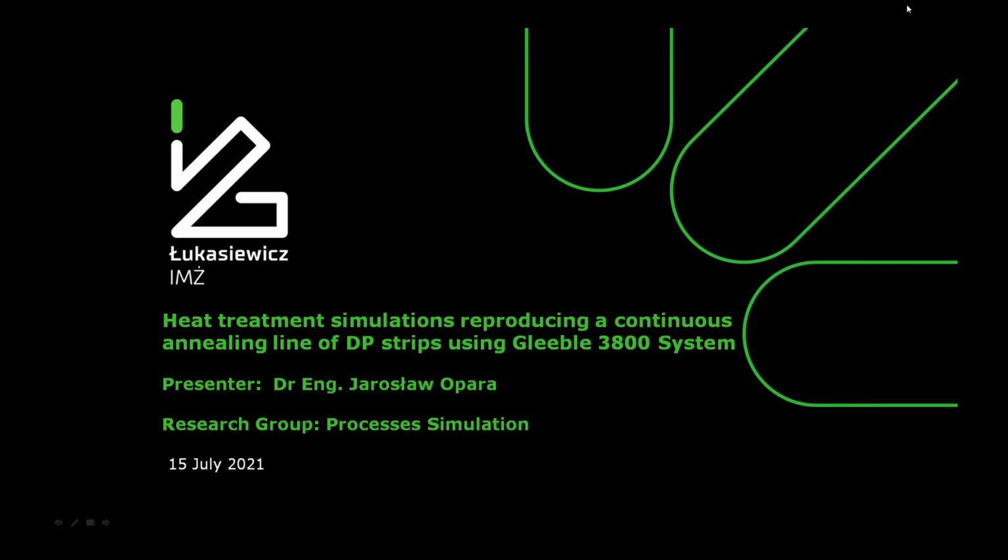Simulations of heat treatment in the Gleeble 3800 will be demonstrated with the application of different parameters which fall into two categories. The first category embraces annealing over a two-phase temperature range followed by water cooling, and the second is the same but succeeded by tempering. Furthermore, two kinds of samples will be depicted, one with a standard 2-inch specimen and the second with a modified shape.